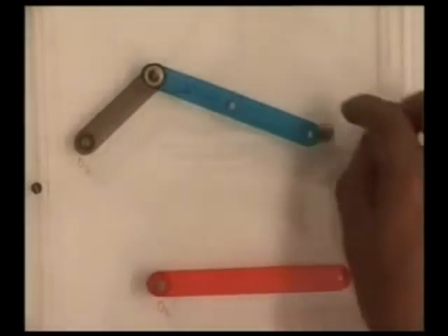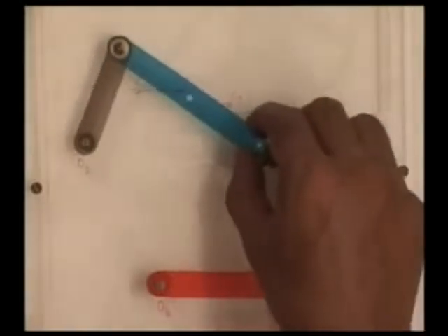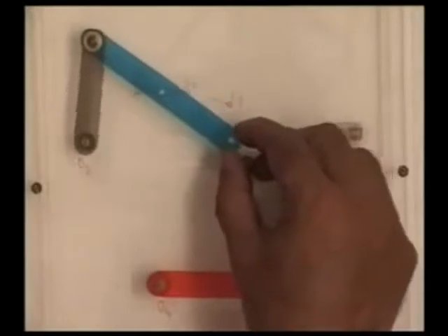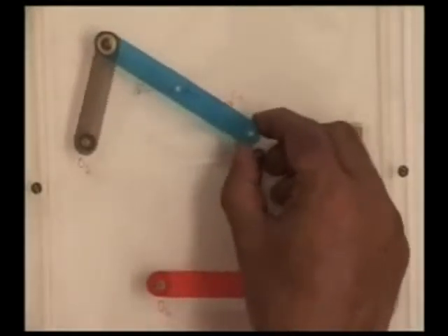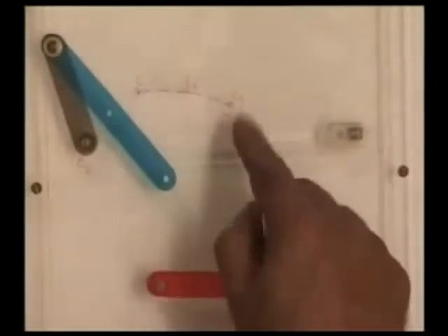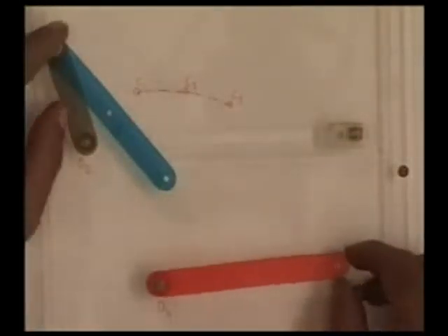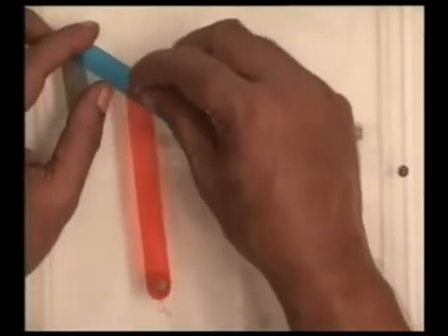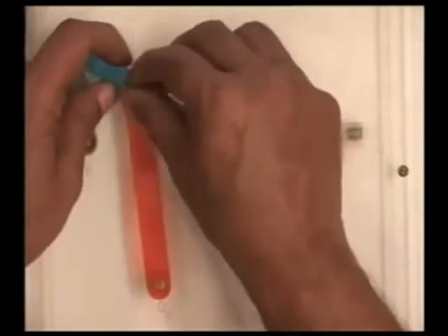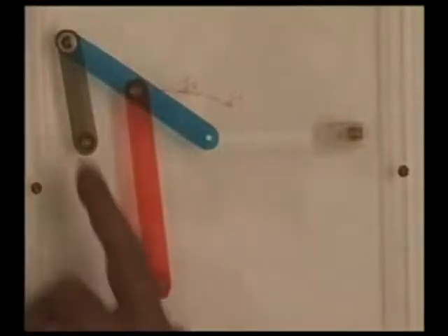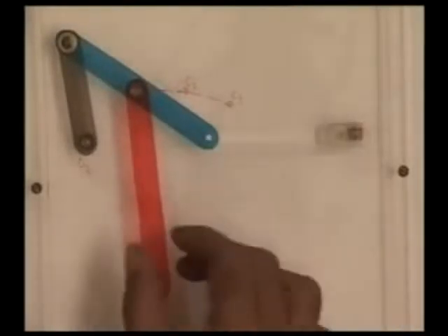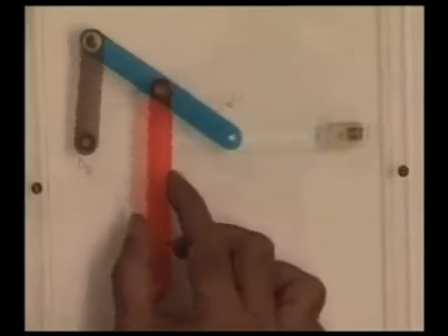Then we removed the slider and considered the midpoint of this connecting rod. Corresponding to these 3 positions, it is at C1, C2 and C3. The center of the circle passing through these 3 points is at O4. So we added a 4th link with O4 as the fixed hinge and connecting it with C1. So we get a 4R linkage with this coupler point generating an approximate straight line as we have seen earlier.